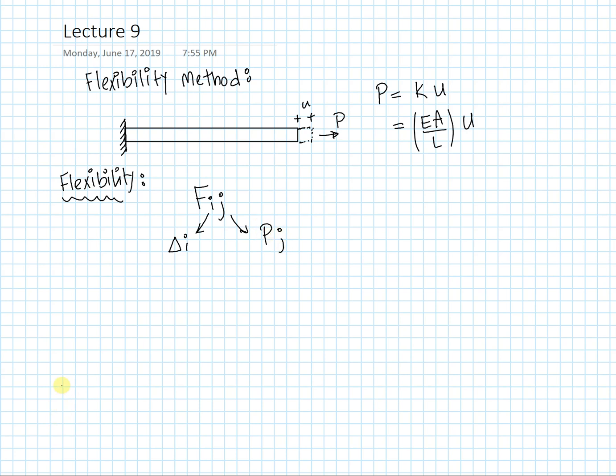And this relationship can only be defined and derived for elements that are stable. So if I give you an element, if I give you this mass, or perhaps this beam that was sitting on two rollers, and I tug on this roller setup with a force P, there is nothing there to resist the lateral exertion of P. And so this element can move and have a rigid body motion. This is what we call a rigid body motion. And in such cases, we cannot obtain the flexibility matrix. The flexibility matrix is non-existent.